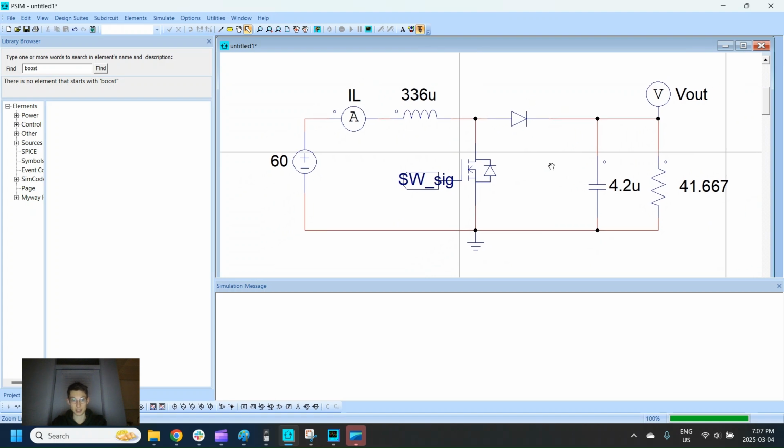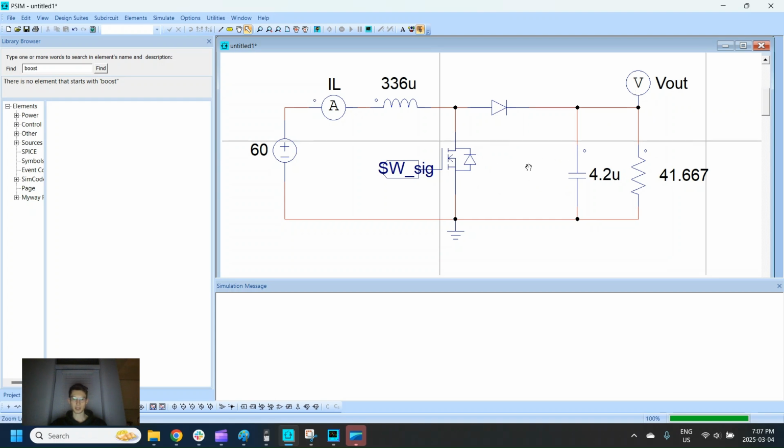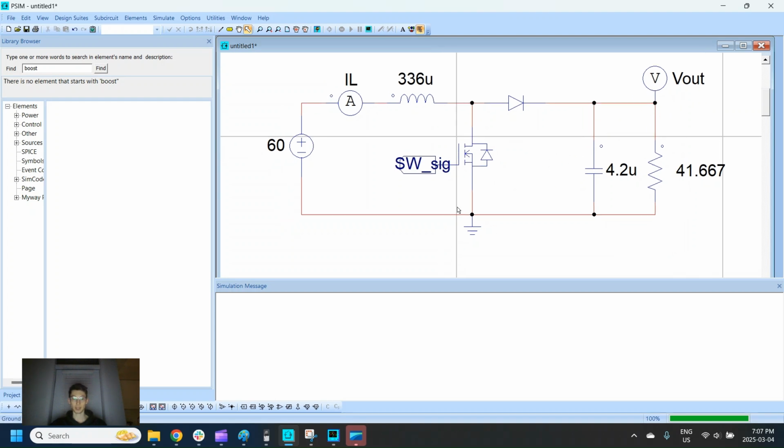The other thing that we're going to need is probably a voltage sensor at the output. It would be nice to have this. So if you have the voltage sensor at the output, you can basically make sure that this is outputting the voltage that you want it to do. And we can add a little bit of feedback in there. I know that you've probably already dealt with some simple voltage sensors. You can also just do a voltage divider down into some microcontroller pin. But it would be nice to, on a PCB, have the voltage sensing capability. And then in your software, you can adjust your duty cycle, things like that.